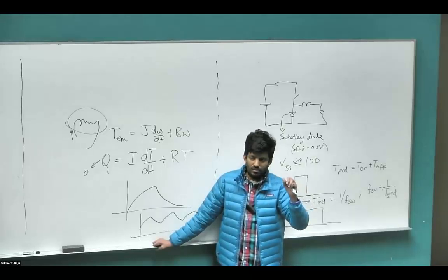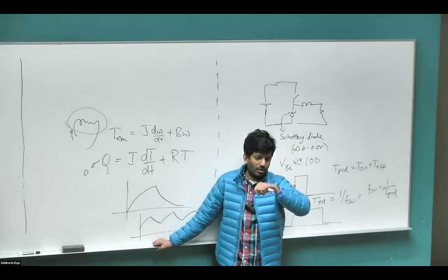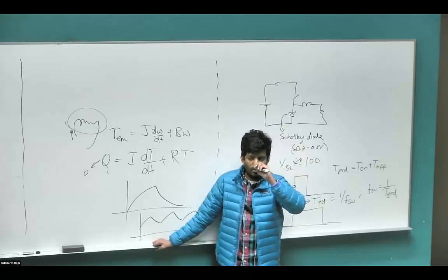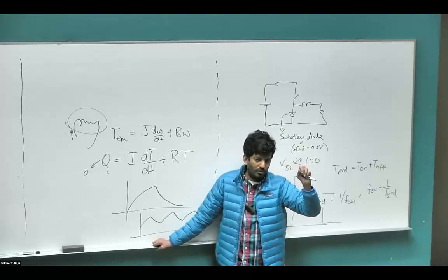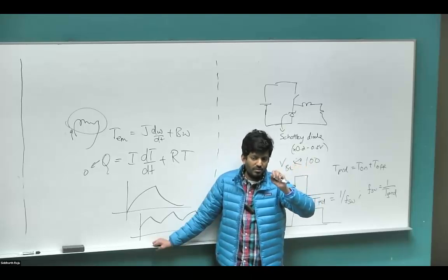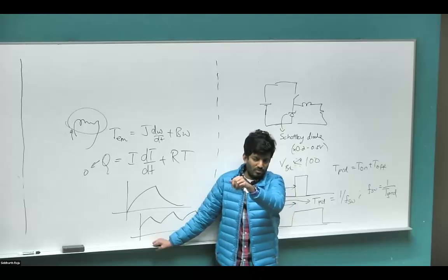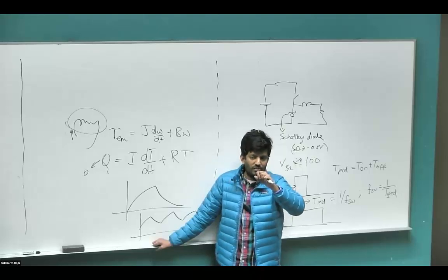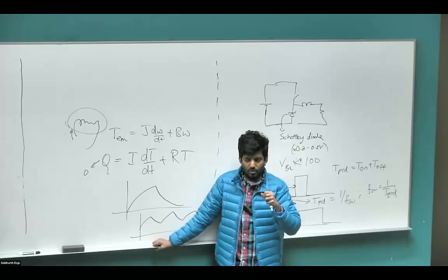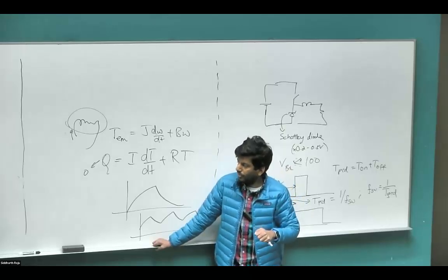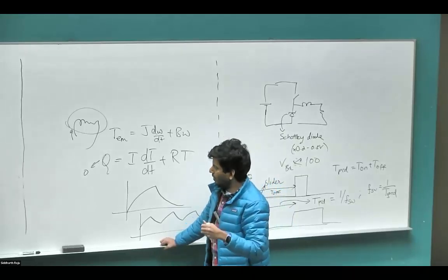All right, this is the thing we'll use in control systems again and again, where we have two control loops, where one controller is doing current control, and then there is an outside cascaded controller that's doing speed control. We would make some simplifying assumptions about how this operates, same as what we are doing here. If something inside has done a good enough job and smoothed it out, we don't need to worry about the system. We can assume going forward that we won't see any flicker or anything. Same in motor control, we won't see any pulsation in the speed because of changes in the current and so on and so forth. All right, so this is called cascaded control.